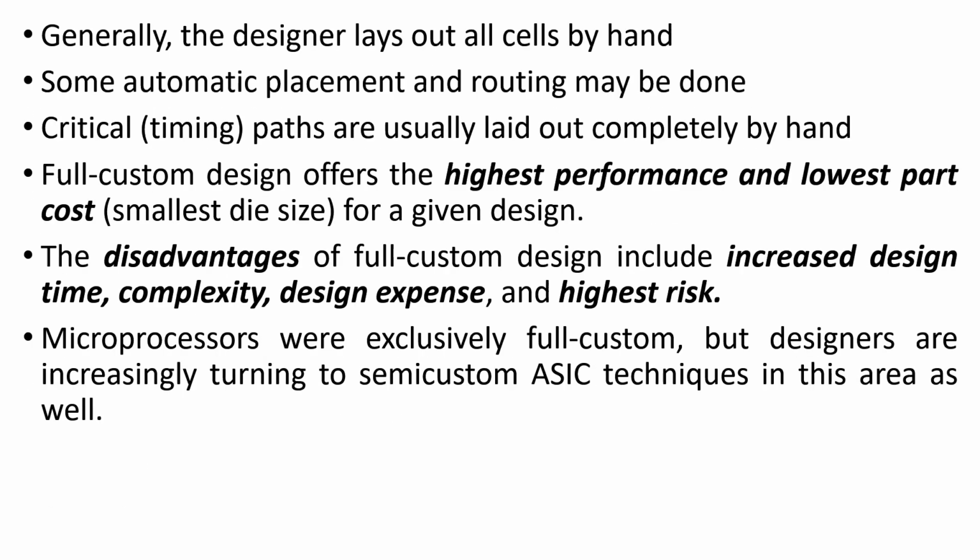Generally, the designer lays out all cells by hand, and some automatic placement and routing is also done additionally. The critical timing parts are usually laid out completely by hand. And this full custom ASIC design offers the highest performance and reduced cost for a given design. The main disadvantages of this full custom design include increased design time, design complexity, design expense and highest risk.